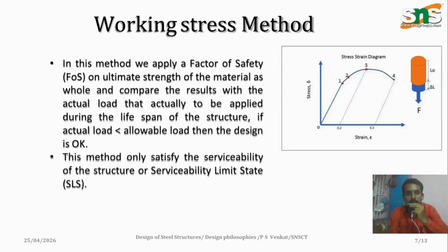We move to the concept of working stress method. In this method, we compare the actual load acting on the structure with the allowable load. If the load on the structure is less than the allowable load, the design is considered to be safe. However, this method satisfies only serviceability, meaning it ensures no excessive deflection or cracking, but not ultimate failure and safety.